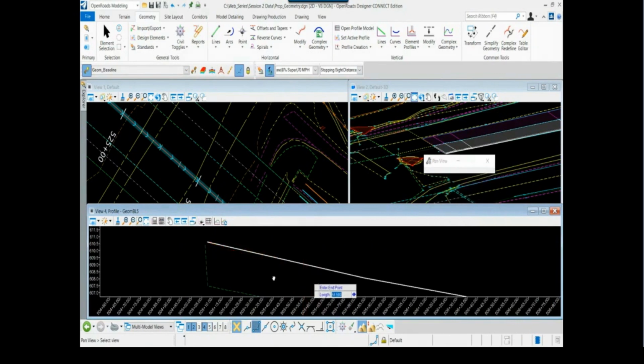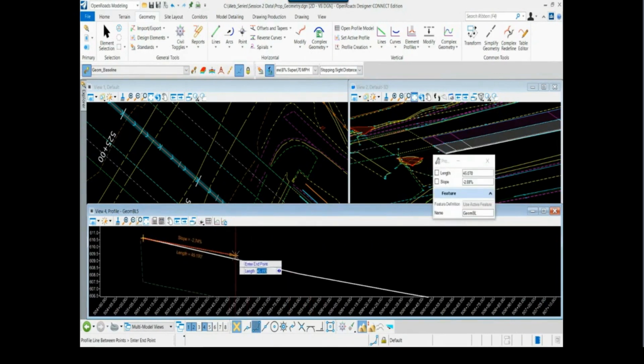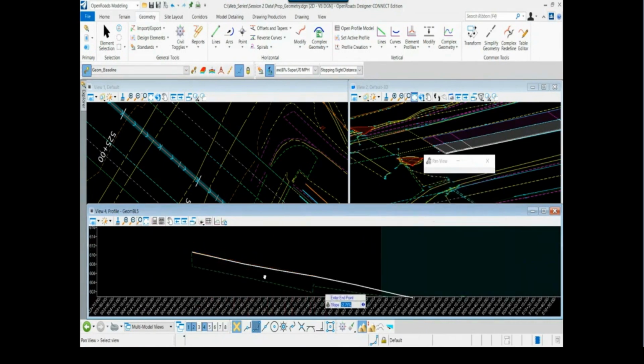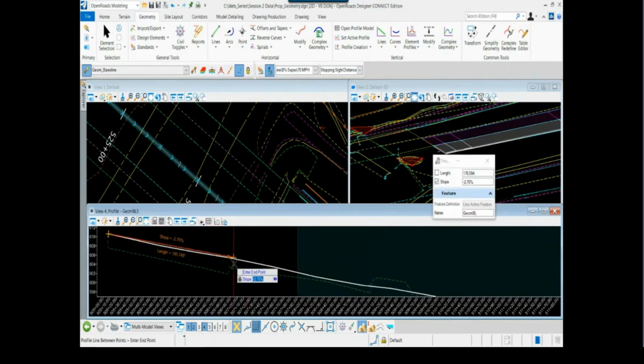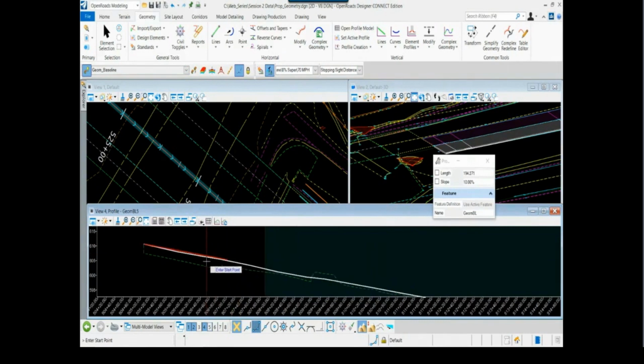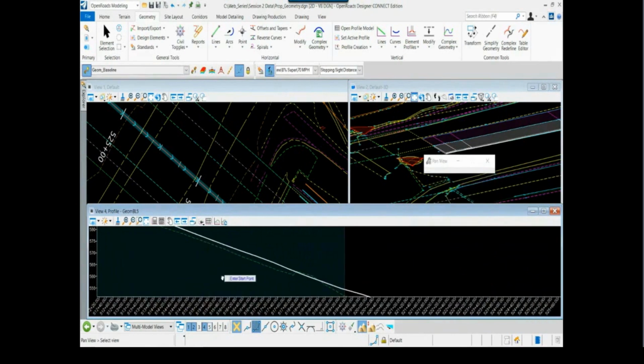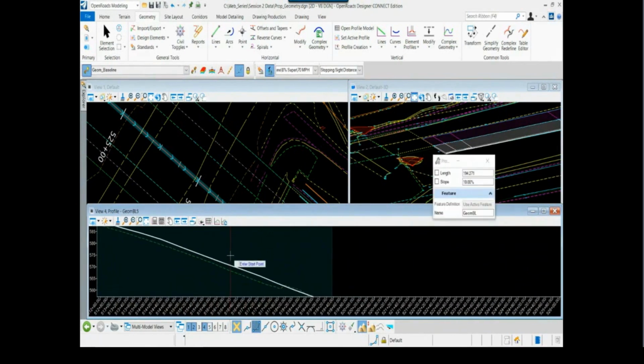Now, as we're laying out this element, I'm going to place tangents, and then fit arcs between them in this workflow. So this first element, we can draw this out. I'm going to hold to a 2.75 grade. So I'll key that value in, and you can see that value. I can actually zoom out. You can see that it fits a little better than maybe it appears. And then draw that segment in. So I have a tangential segment along that edge of pavement, that proposed widened edge of pavement using the existing cross slope of the road.